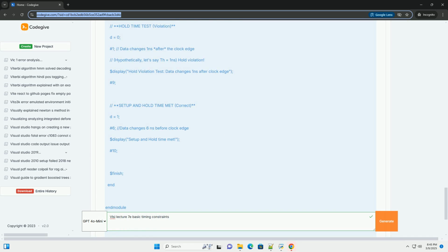Retiming: moving registers around in the circuit to rebalance the path delays. This is usually done automatically by EDA tools. Gate sizing: changing the sizes of transistors in logic gates to increase or decrease their driving strength and delay. Floor planning and placement optimization: improving the physical layout to reduce interconnect delays.